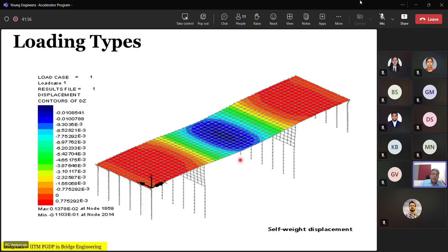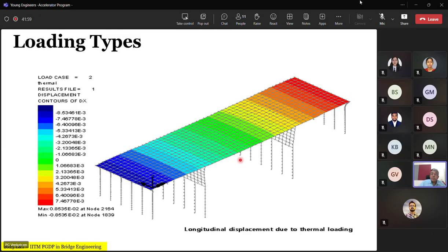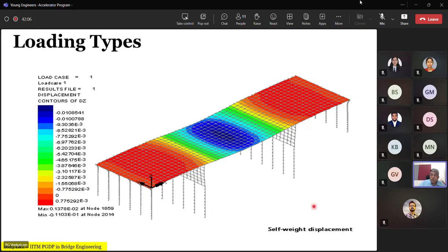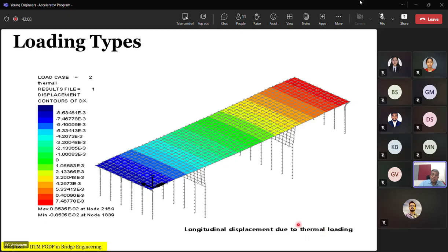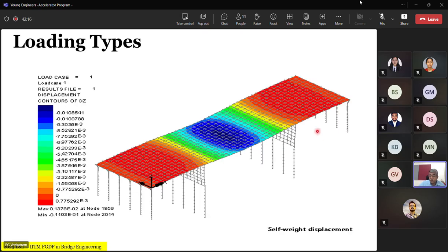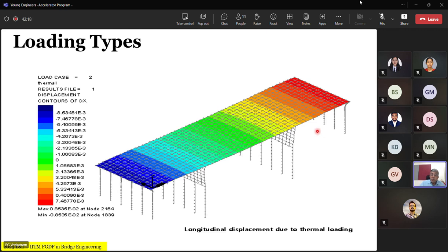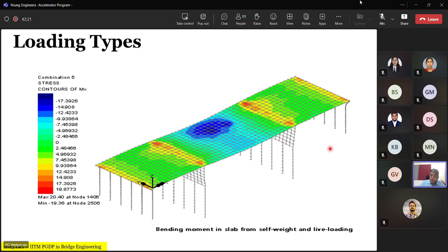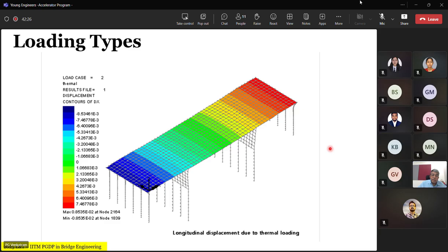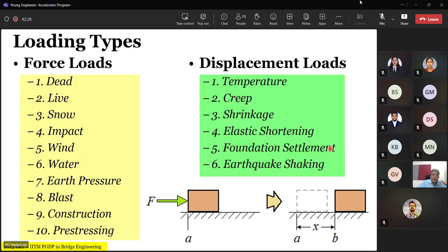So you have even gravity loads causing longitudinal movements in the deck. Even gravity, as you can see from the self weight, as long as you have a deck which is monolithically connected to the superstructure. So therefore, you cannot ignore the longitudinal deformation of the bridge, and that important activity is covered by the arrangement which we call the arrangement at the joint.